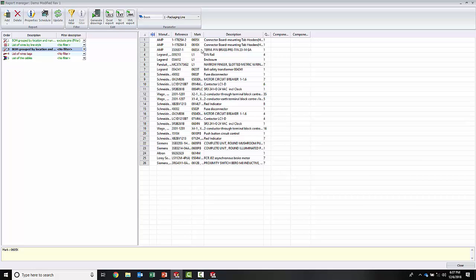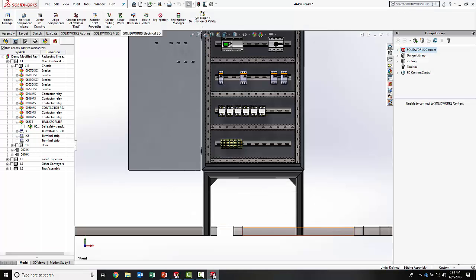Of course, you can use one of those user data fields to put in a cost per length. Because of course, the duct and the DIN rail in 3D give you the length. What you also get is that 3D will push those lengths back to electrical, and then you'll have that data. Then you can calculate it using the report to come up with all of that information.